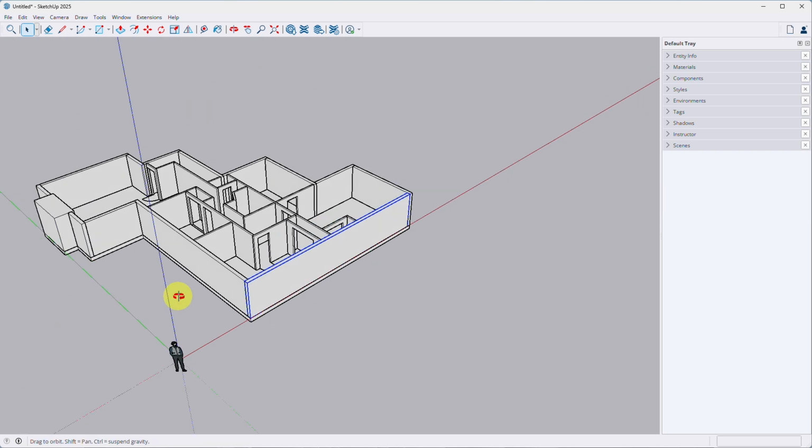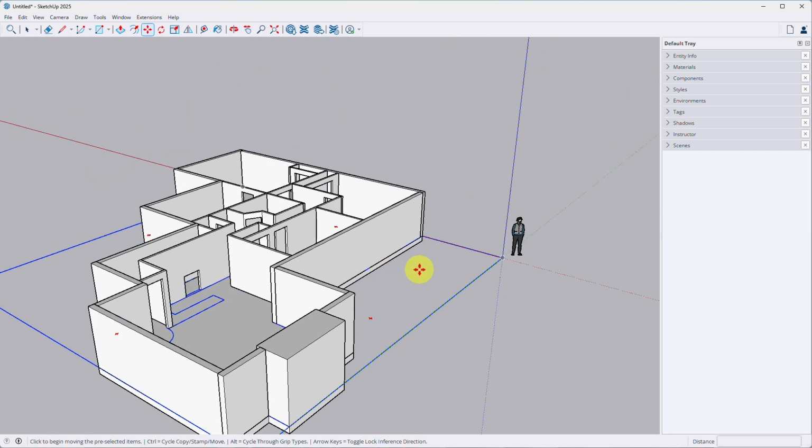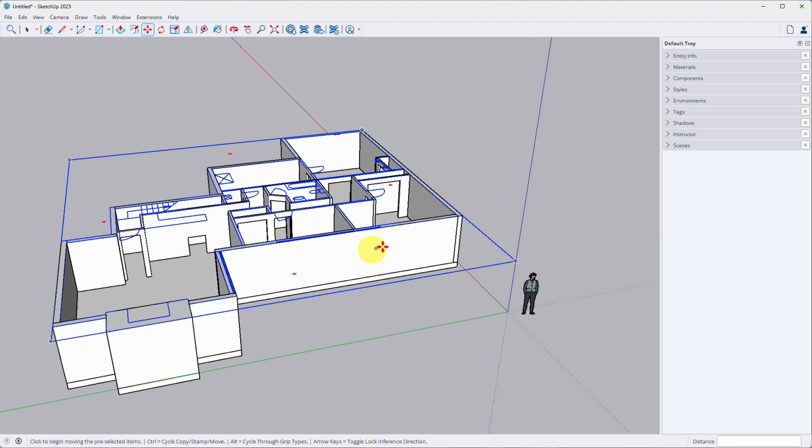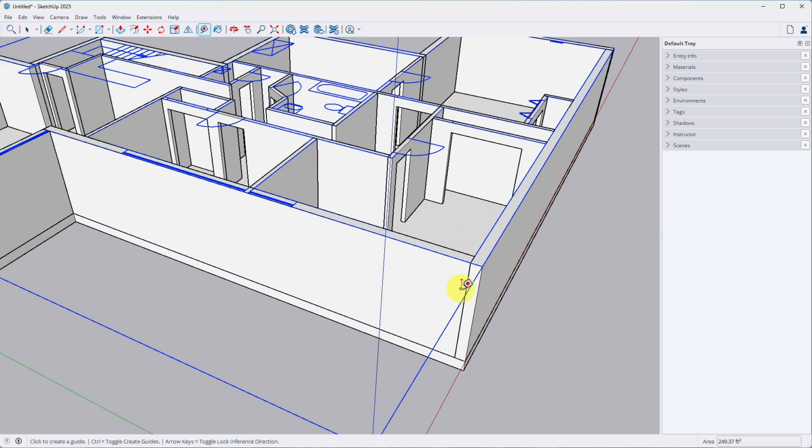We create the window openings in the same way that we created the door openings. Raise the plan to the top of the walls so we can see the extent of the openings. Then create vertical guides to the extent of the windows widths.